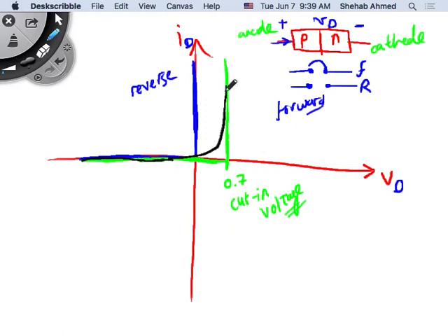It's the point where, using your external circuit, you were able to overcome the barrier voltage. You have a barrier voltage that was reduced using an external forward voltage. Both of these together cause the barrier voltage to decrease, and you were able to start conducting current by diffusion.